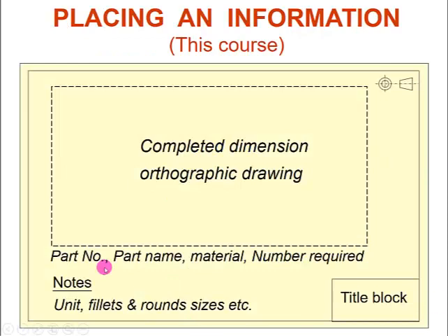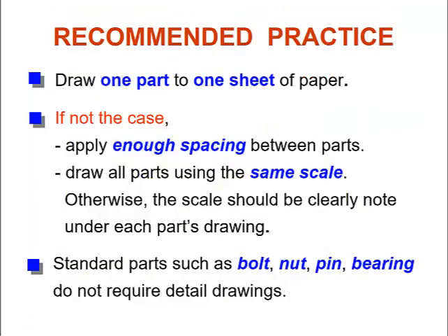Okay, this is your paper sheet. So when you place your title box, it will be out there. The things I would like you to do, you need part name, material type, list, and method of your projection. Okay, that's what you need to put in your title box.